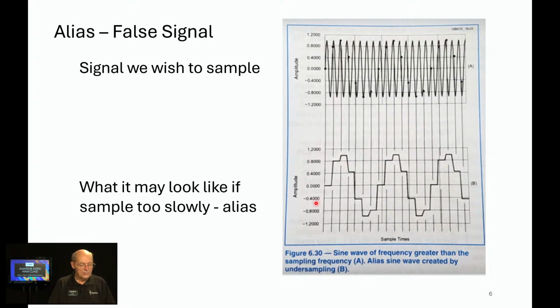And you'll see that the recovered waveform, this waveform right here, has no resemblance whatsoever to the waveform that we were originally trying to sample. And that's because of aliasing. So this will generate an output, and this will be absolutely real, and it'll really confuse the electronics and your ears if it happens to be in the audible range. So this is a little picture of what that means and why we don't want it.